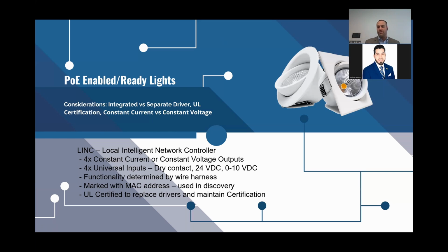So Gary's going to ask a question. If you're at home or on Zoom, go ahead and raise your hand and I'll come to you and I'll answer any questions about the main components. So on the constant voltage for dimming, is it a pulse width dimming? Yes. So it's not like trying to get it down to 12 volts to dim it. It's just the amount of on time versus off time. So Gary's asking if it's pulse width modulation that we use on constant voltage to adjust the dimming.